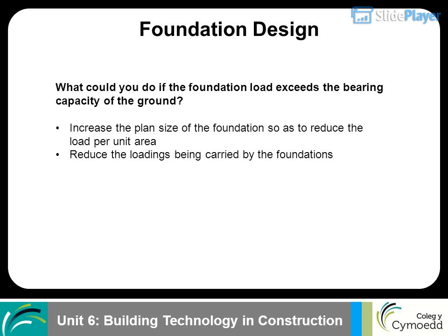Foundation design. What could you do if the foundation load exceeds the bearing capacity of the ground? Increase the plan size of the foundation so as to reduce the load per unit area. Reduce the loadings being carried by the foundations.